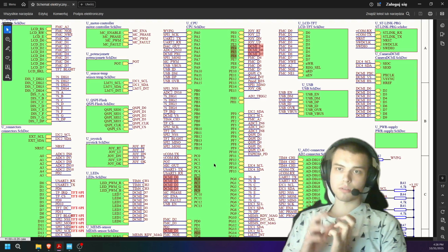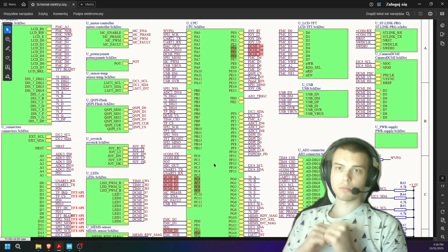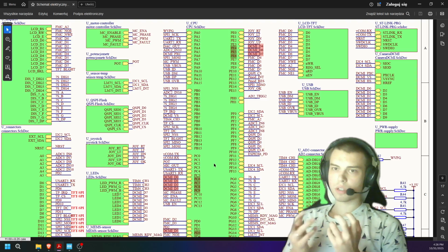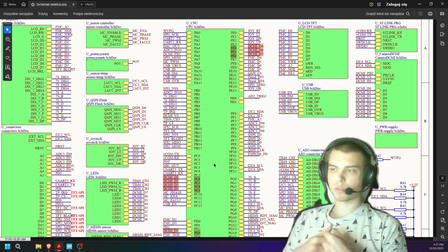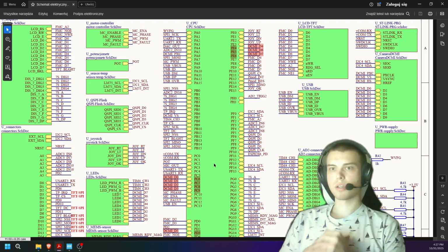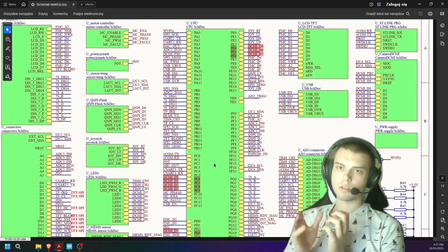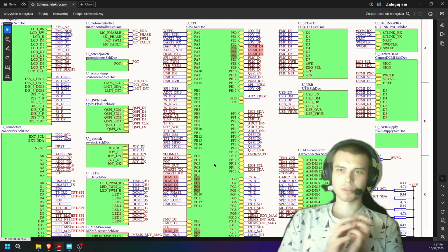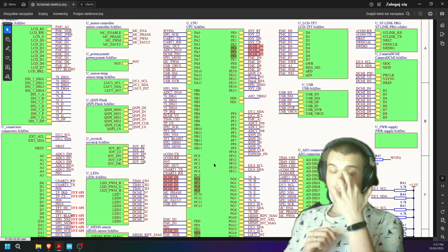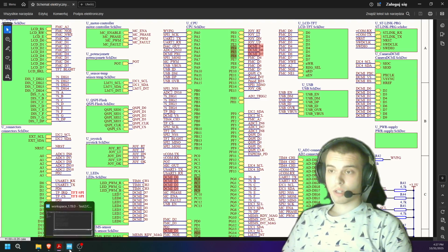On your specific board, it may come in the form of a table of pinouts. For example, diode 0 may be connected to a different port. On your board, it might be port A, not port C. So you have to search for this information, but it's important to understand that there are ports and also pin numbers, and they're different. Knowing that, we go to our IDE.